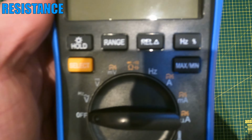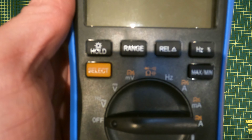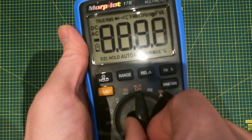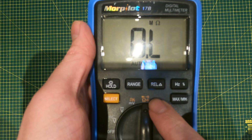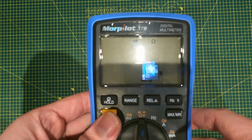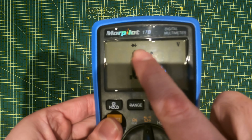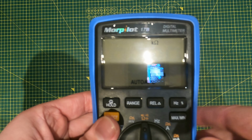Okay guys, the next feature we'll be looking at is the horseshoe symbol there, which is ohms for resistance. And what you do is you use your selector dial to select the feature. This has a couple of features on this mode, so we'll use the yellow select button to cycle through. At the moment it's on the ohms. If I cycle through, just to give you an example, we've got continuity, the check diode feature, we've got capacitance, and then back to the ohms.